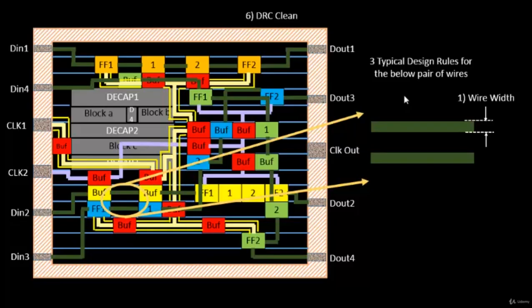Considering that, we come up with certain rules, and the rules say that the optical wavelength of the light is so small that the minimum width of the wire should be at least this much. You can't go below this because it can't be printed. That's what the rule says. It's mostly related to optical lithography techniques, and we will talk a lot about optical lithography in separate videos, in a separate section, where lithography and the DRC rules will be in conjunction with each other, going hand in hand. In this case, let's try to understand a light.